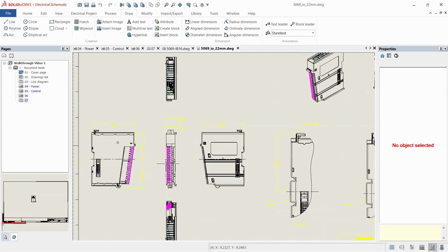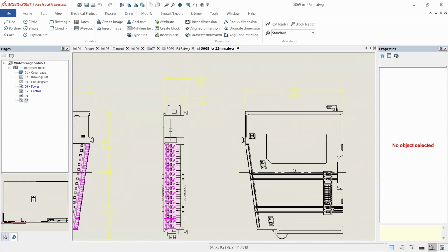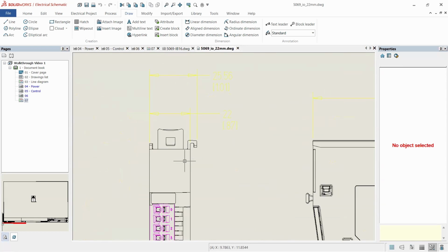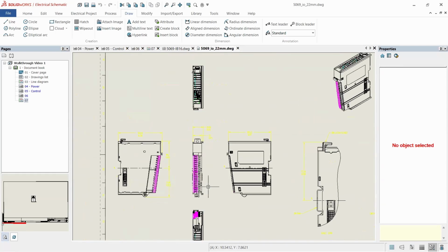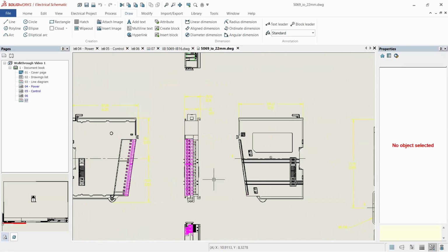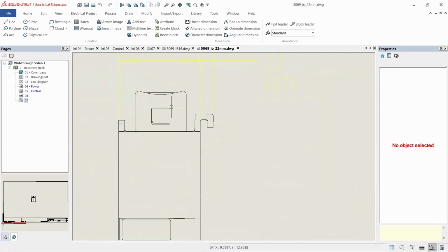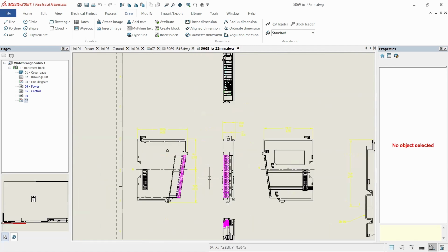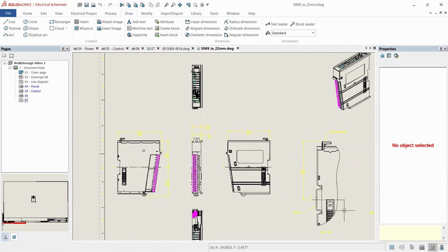We're going to use this for our 2D footprint, and I like to do it this way because if we just look in the PDF manuals, the dimensions they give you are going to be this 22 millimeters, which is the primary width of this card. However, our 2D cabinet layout is going to put a bounding box around our symbol, and it's going to catch everything. So the bounding box is going to go all the way out to the end of this tab, which is 25.56, right? So the 22 isn't good enough. Also, if we look at the side view, the height also, where is the height dimension called out here?